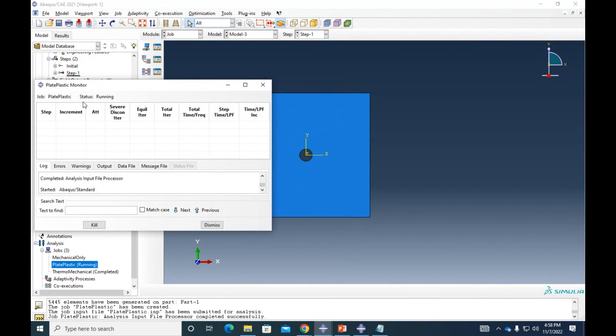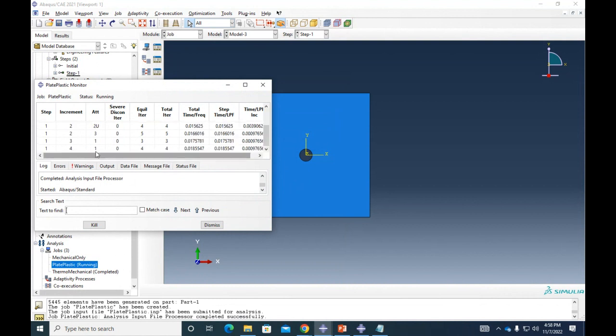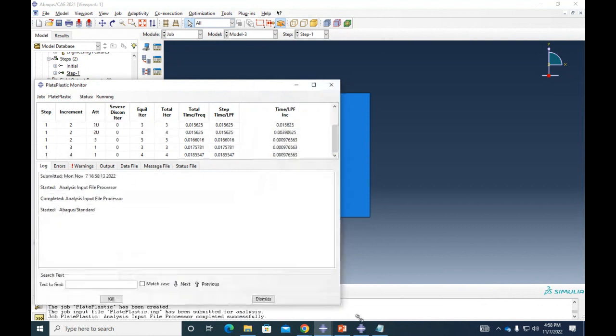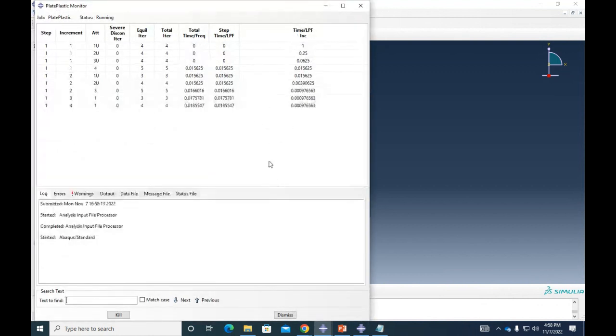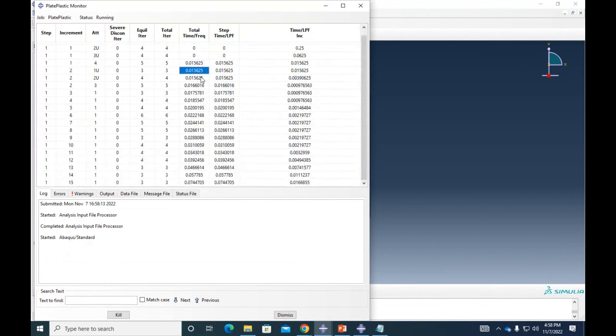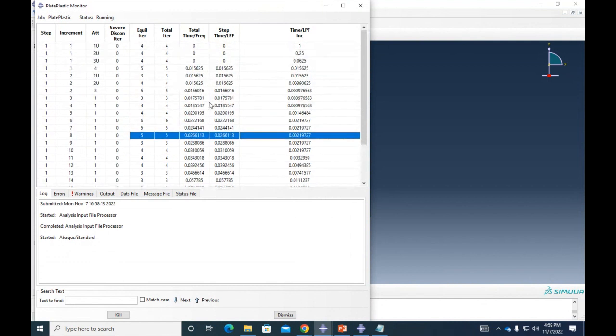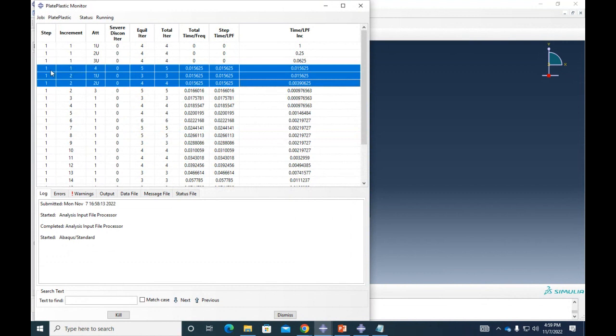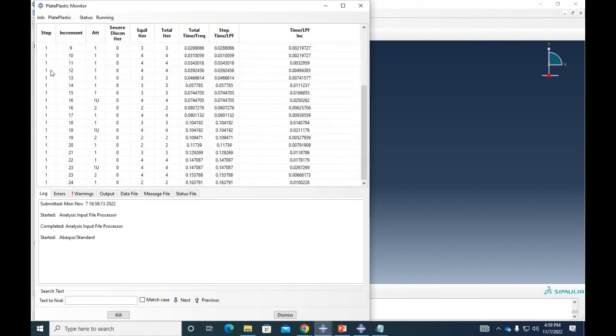Where do you think that this is gonna start yielding? It says stress concentration. Nice. So now, instead of having a single increment, look at the way that Abaqus is applying the load. First, it applied 0.05% of the load, then 0.05, and in here, Abaqus stayed for a while, right? Trying to apply this load. And the reason for that is the solver didn't converge. So this is a really complicated problem. Even though it doesn't look like that, it is a complicated problem.